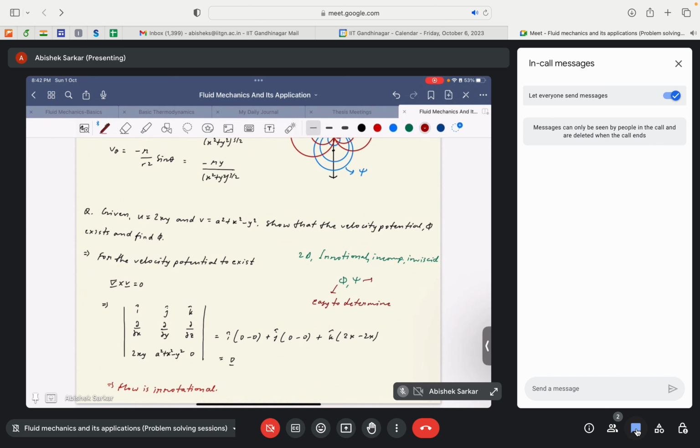And psi is easy to visualize, because we discussed very extensively while discussing the flow kinematics part how streamlines help in visualizing the flow. First of all, the streamline is, by its very definition, an imaginary line that is tangent to the velocity vector at each and every point in the flow field. So by that context itself, it helps us in realizing the direction of the flow field.